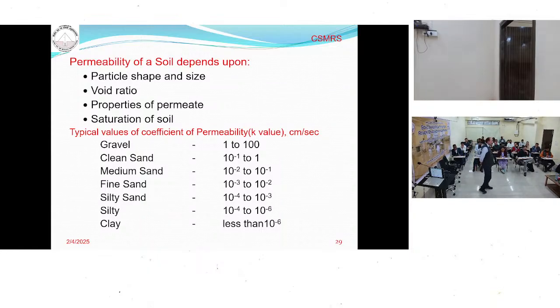Depending upon the particle size, again, from the morning, we are coming back to particle size. Depending upon the particle size, the permeability will vary like this. If you talk about clay, the permeability is less than 10 to the power minus 6 centimeter per second.